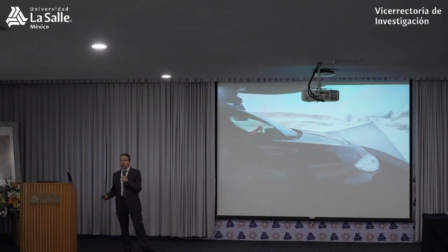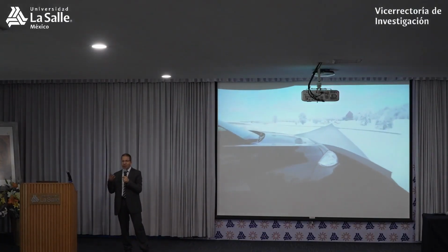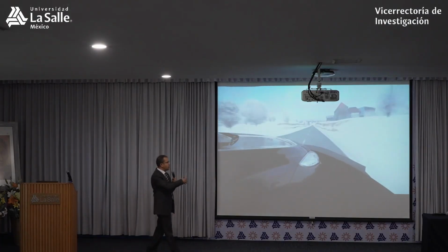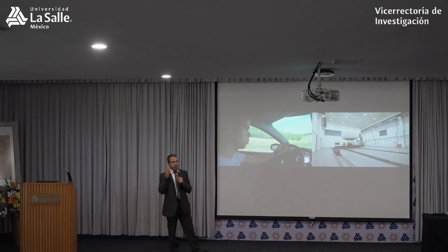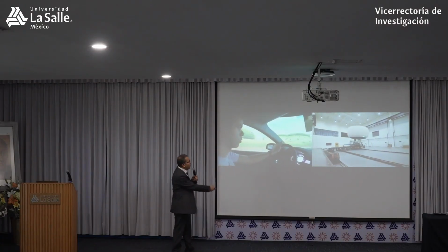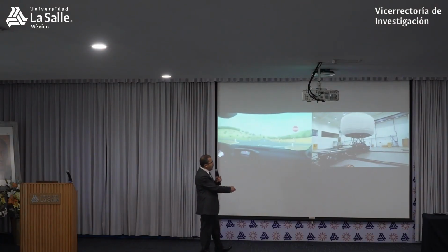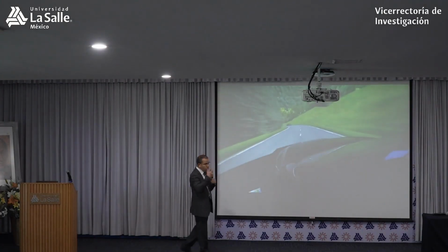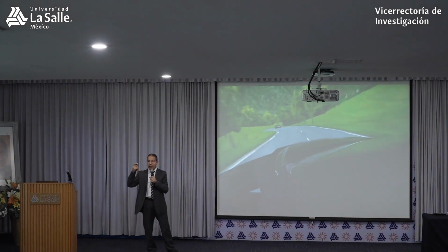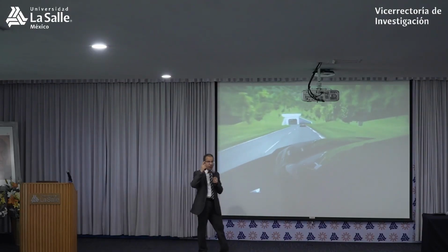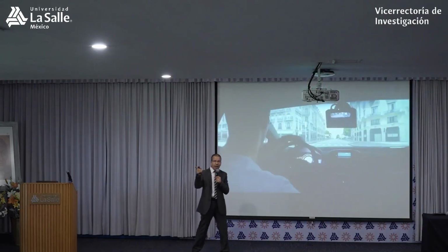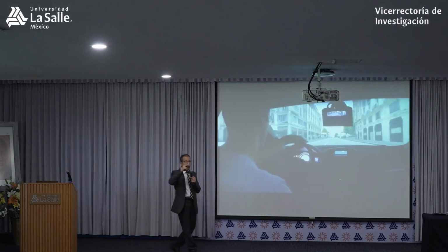The first question you may ask is why we use those robots for this specific application. Because those robots are reputed for their high payload capacity. You can put a huge payload here, and then you can control the parallel robot to move this payload in 6 degrees of freedom. The workspace is small, however the number of degrees of freedom is 6, so you can have X, Y, Z, and also roll, pitch, yaw.